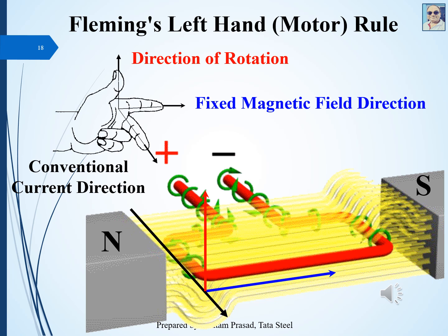You can observe here that you are feeding the left terminal with the positive terminal of the battery, and the right terminal with the negative terminal of the battery. So the direction of the current has been reversed as compared to the earlier slide. So you are seeing the reversal of the current. If you interchange the positive and the negative terminals of the coil, then it will exactly change the direction of rotation of the motor. You can see it practically; we show it in the labs by connecting the motor and interchanging its terminals.